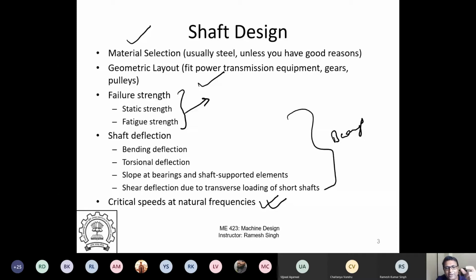So that kind of a component, if you run at natural frequencies, you run a risk of damaging the rotating equipment. So you need to understand what will be the critical frequency of the shafts and try to avoid it. That's very important. For any rotating equipment, understanding the critical speeds is a very important concept. So I'll give you some first order approximations. How do you decide what will be the critical frequencies, and some of the discussions, not very detailed, but both via finite element modeling and analytical modeling I'll share with you in this class.